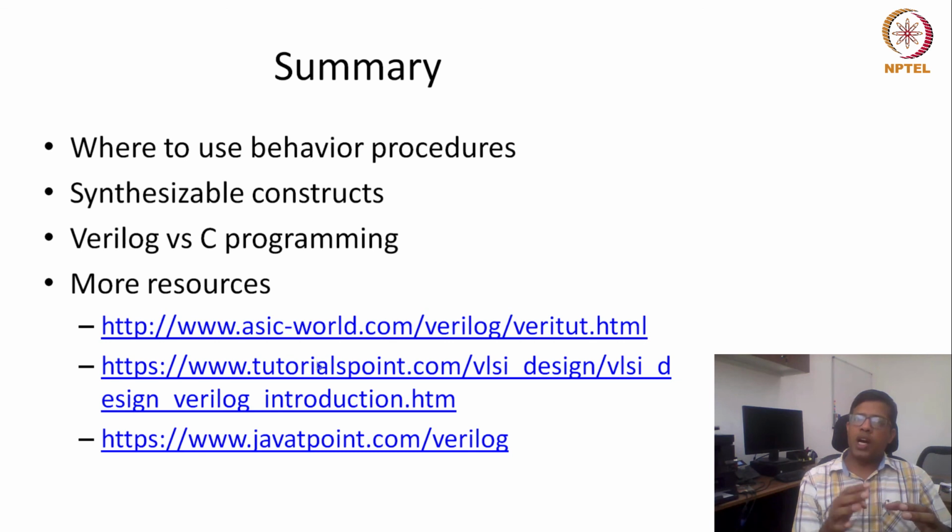However, if you are modeling hardware, we have to visualize, or write on paper, what my hardware module is going to be, what kind of operations will be there, how many cycles it will take, etc. All of those things can be done if we are using either a structural model or a data flow model.